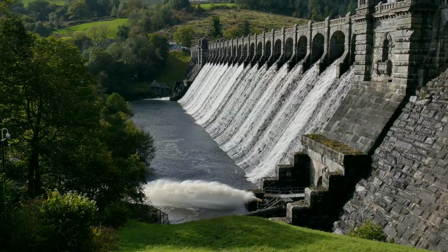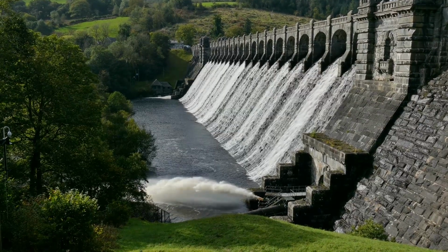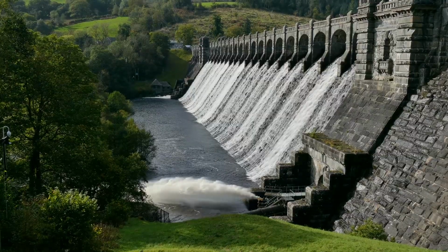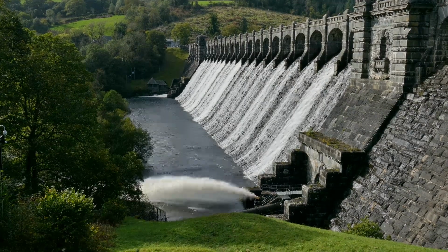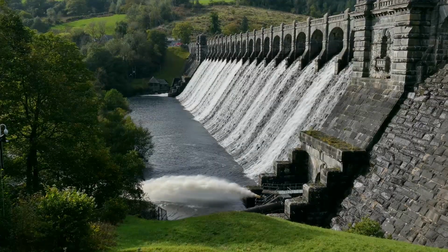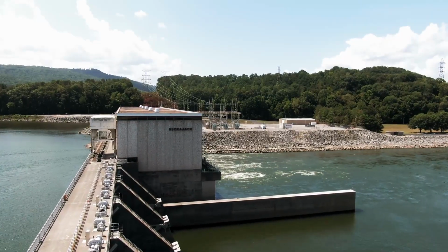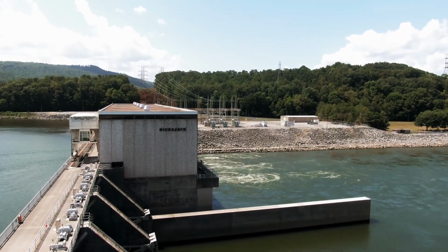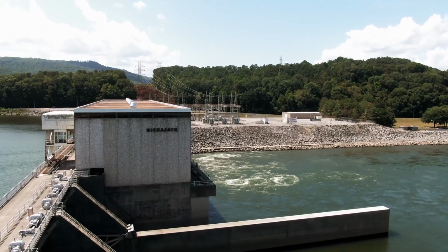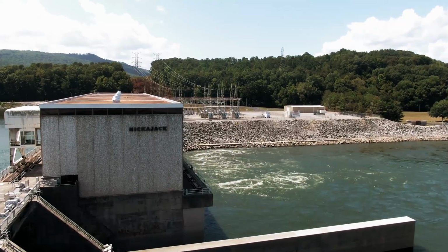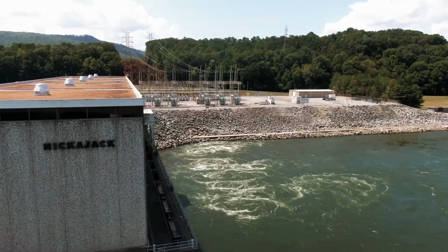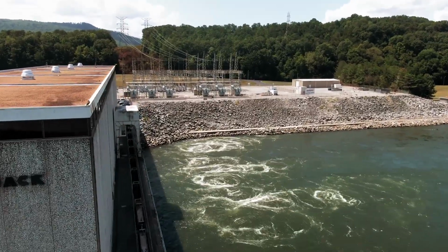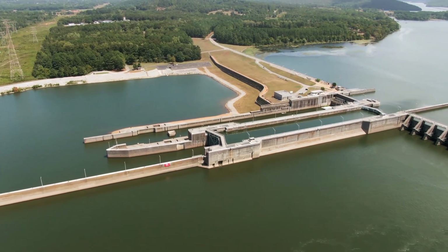Then next we make sure that we select the spillway type. Before calculating the size, engineers select the type of spillway. The common spillway types include ogee spillway, side channel spillway, shaft spillway, siphon spillway, and labyrinth spillway. The selection normally depends on the dam height, the foundation conditions, the site topography, and the required discharge capacity. But many dams use ogee spillways because they efficiently pass large floods.